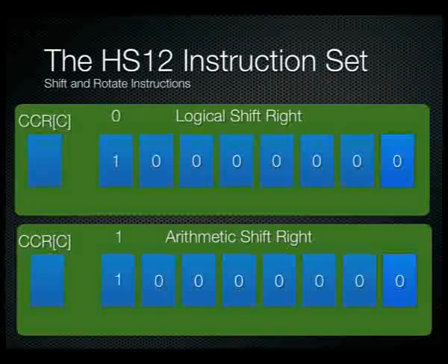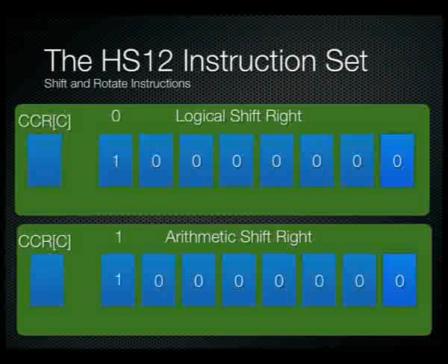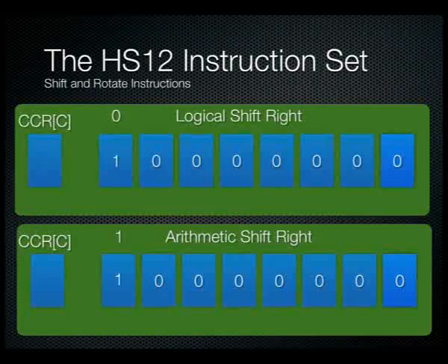If you're not sure, arithmetic shifting is the safest bet, unless of course you know it's a logical number that you've read out of a register and you just need to rotate it or move it around, then of course use logical shift right. So depending on the application, make sure you use the right command.